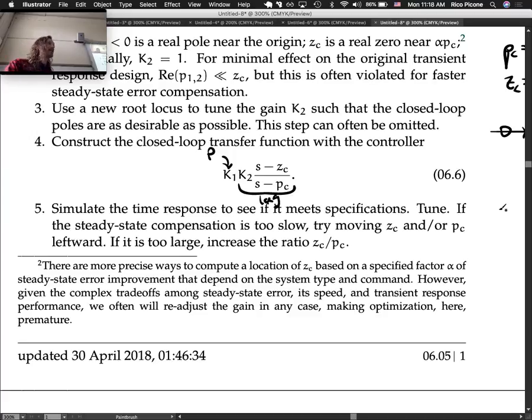So instead of going into software, you can take the voltage output. Say you had an analog encoder. Let's just imagine this scenario. We had an analog encoder, so it just gave you a voltage that was proportional to the angle, and then you put it into a circuit that was like a bunch of resistors and capacitors. And the Nise textbook actually shows you how to instantiate a proportional lag controller in a circuit.